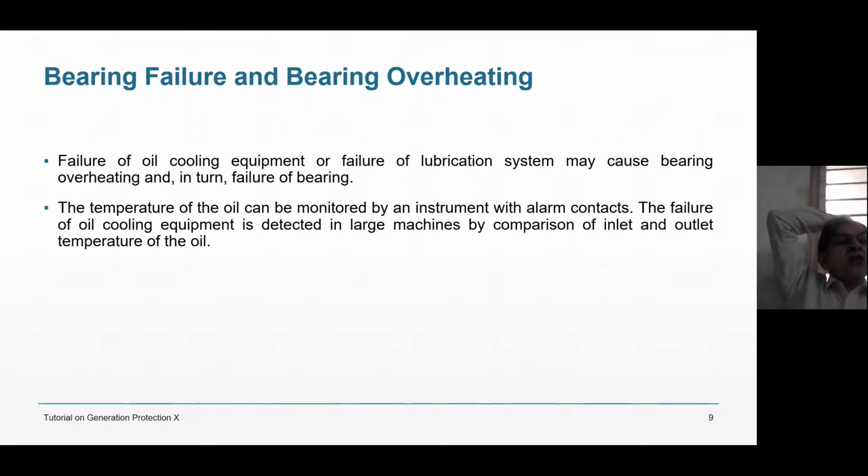And that oil has to be replaced because it is heated, and it will be taken to coolers. It will cool and come back to the bearing. That loop circuit will continue. So if that bearing fails and overheats, that is an abnormality, because of which an alarm can be sounded, or if things are too much out of control, then tripping also can occur.